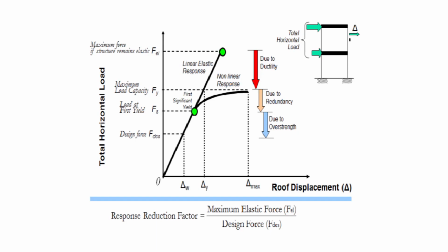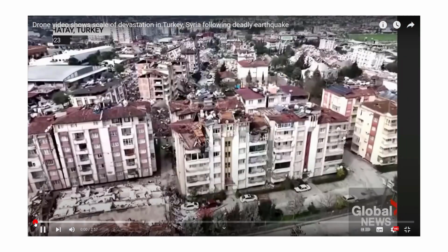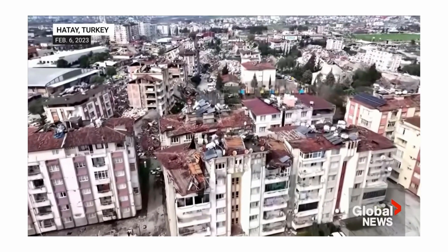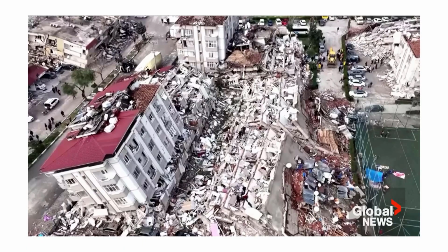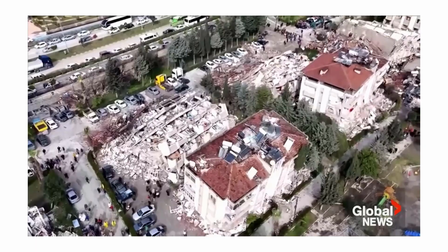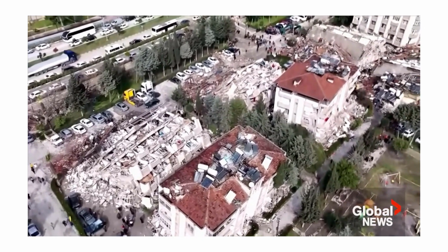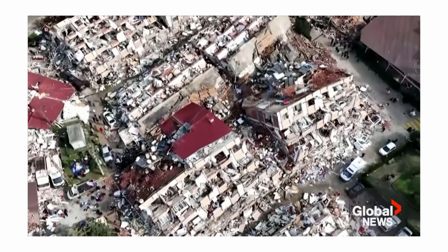So most of them were found to be non-ductile and failed like a typical brittle structure. So what went wrong? Okay, so the collapsed buildings were designed based on the reduced earthquake load, that is, using the response reduction factor R by relying on the ductility and overstrength of the material used.